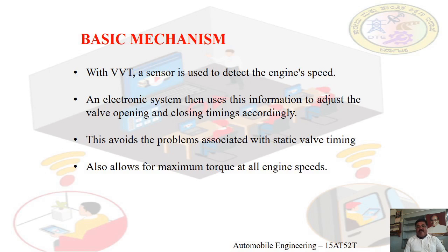It adjusts the valve opening and closing timing accordingly, according to the valve timing diagram. This avoids the problems associated with static valve timing. It also allows for maximum torque at all engine speeds.